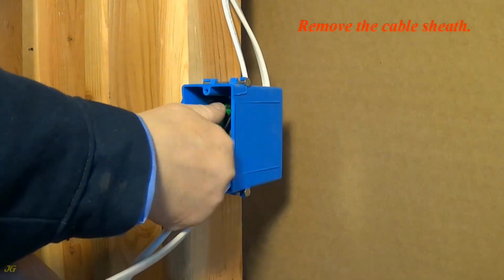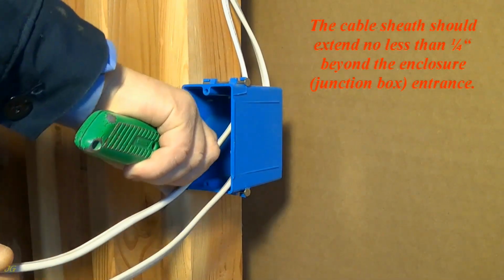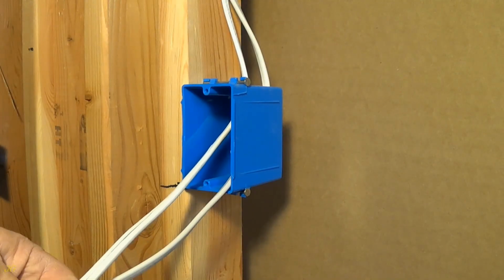Remove the cable sheath. The cable sheath should extend no less than 1/4 inch beyond the junction box entrance.